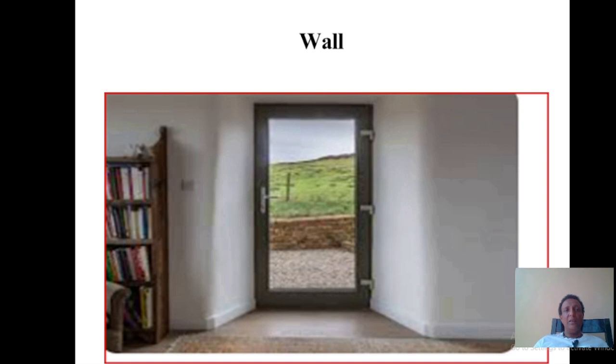Exterior walls are exposed to external reactions, so they have to be strong enough to resist those reactions from the external environment. In the case of internal walls, they have no direct relation to the external agencies, but they have to absorb noises, provide acoustic balance, and also be fire resistant. The function of walls is to separate spaces vertically, and some walls are also expected to carry loadings.